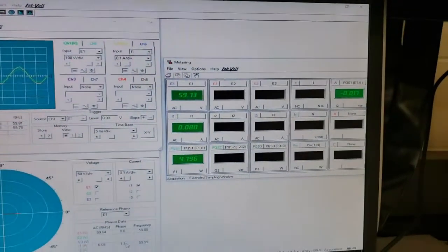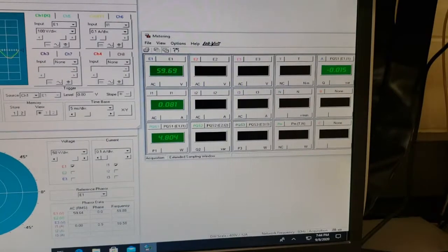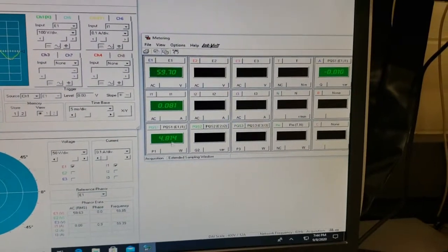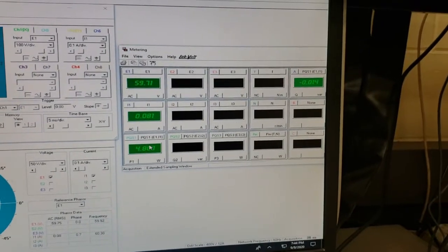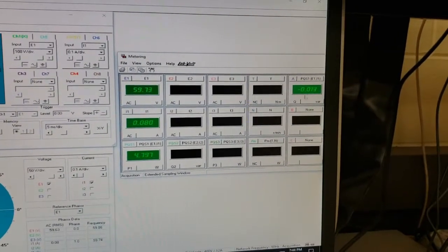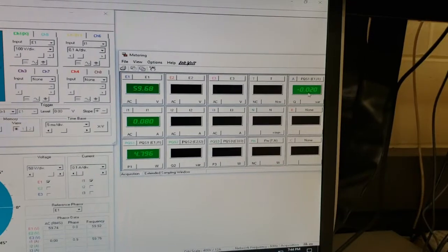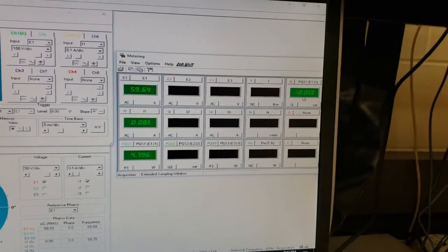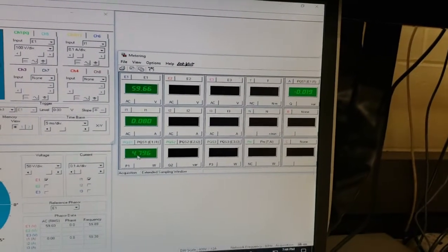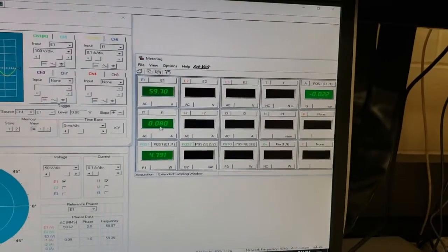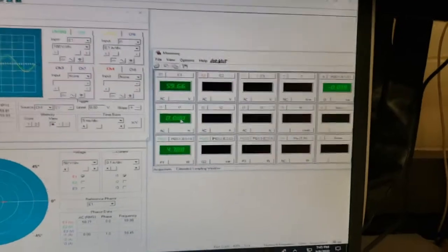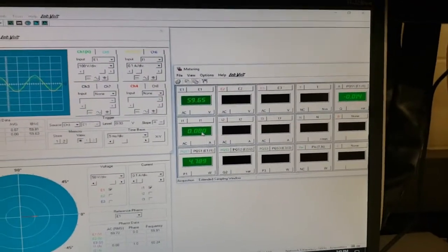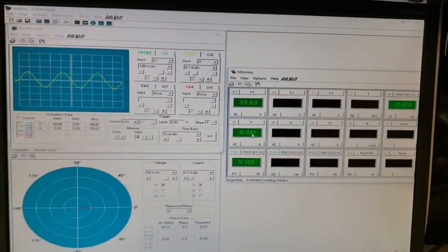And once I turn on the needed amount, the needed impedance, you can see if I go back here, right away, everything seems to be corrected. The real power is about the same. Maybe it's a little more because the inductive load has some resistance, so it consumes some real power. But look at this. The reactive power draw went from -2 to almost 0 at this point. So it's dropped drastically. We still have about the same amount of current. Actually, no, a little less current, which makes sense. That's one of the features of power factor correction. You reduce the current requirements from your power source.